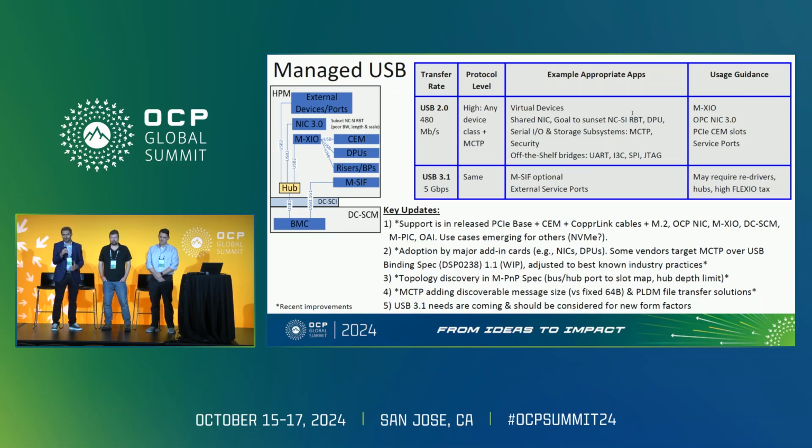Some of the vendors are going to implement this 1.1 specification, which is actually addressing bottlenecks in the large topologies. So we see long-term that those topologies on the USB out-of-band management will be large, and we need to effectively leverage that 80 megabits of bandwidth, not waste it on polling cycles and those types of solutions. So we are fixing that in the MTF. There's a 1.1 proposal.